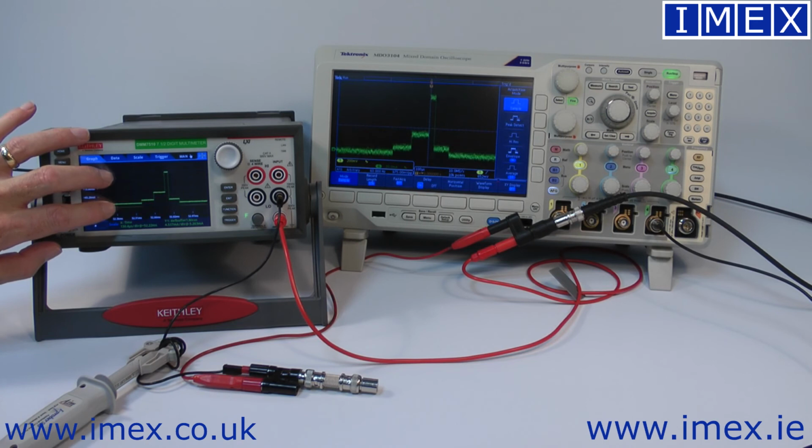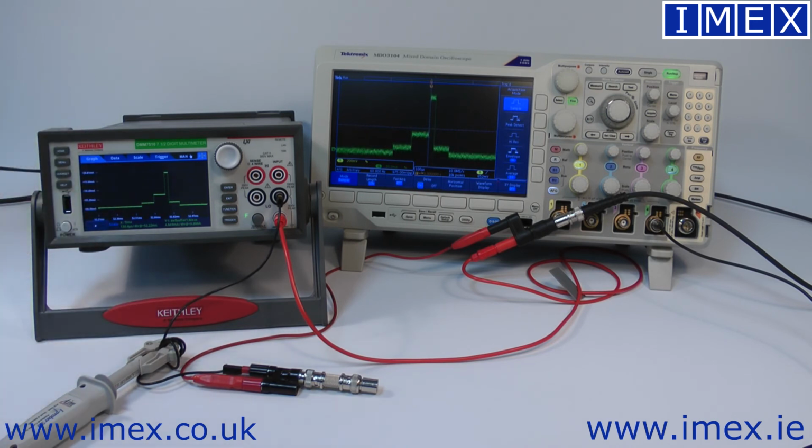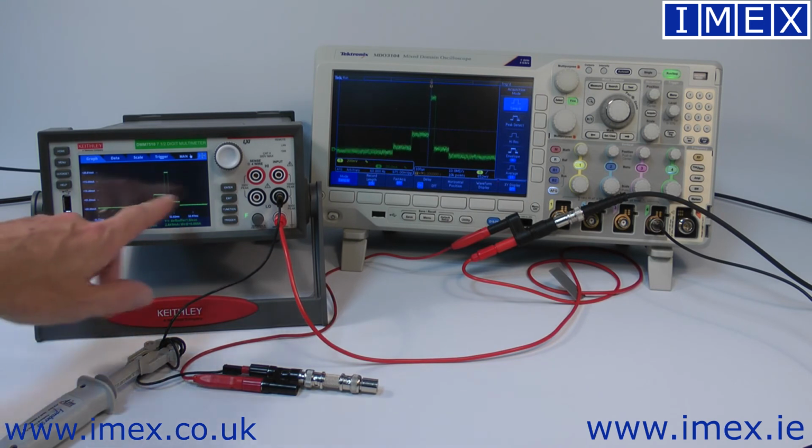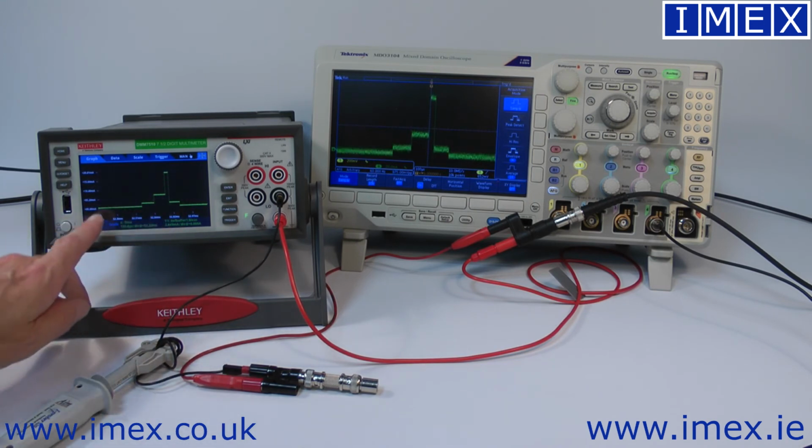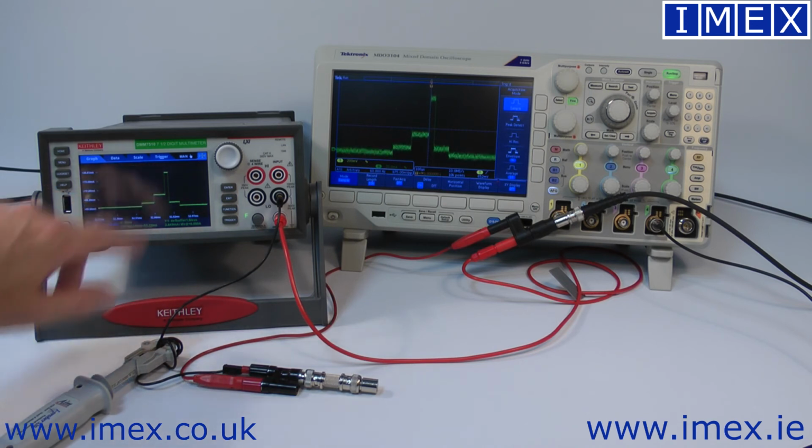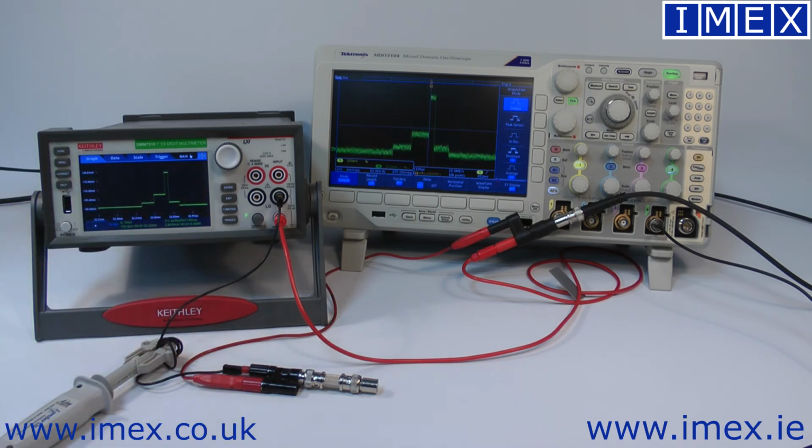So our multimeter is behaving more like an oscilloscope, and yet we have the resolution. You can see there's no noise on that. We can get our low level of our half a milliamp, we can get our 20 milliamp peak, we can see the exact profile of it, and more importantly we can do that over an extended period of time.